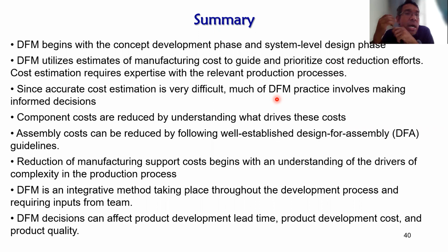So component costs are reduced by understanding what drives the cost. So you need to understand that one. And then assembly costs can be reduced by following well-established DFA guidelines. So a reduction of the manufacturing support cost begins with the understanding of the drivers of the complexity of the production process. And then DFM is an integrative method taking place throughout the development process and requires input from the team.